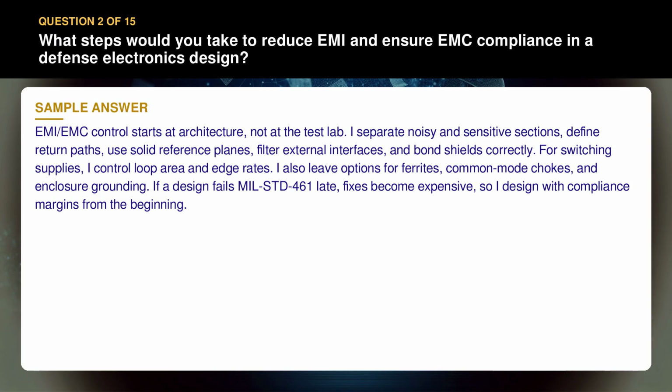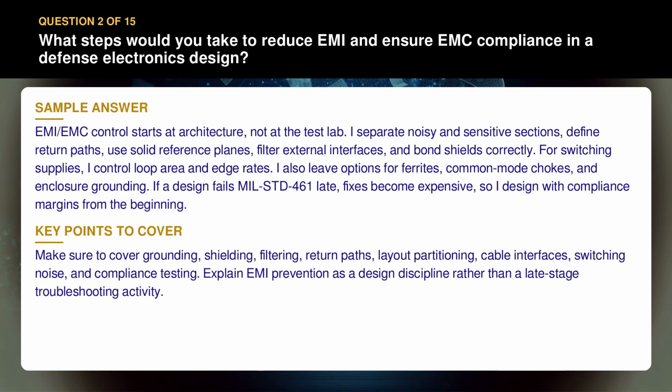If a design fails MIL-STD-461 late, fixes become expensive, so I design with compliance margins from the beginning. Make sure to cover grounding, shielding, filtering, return paths, layout partitioning, cable interfaces, switching noise, and compliance testing. Explain EMI prevention as a design discipline rather than a late-stage troubleshooting activity.